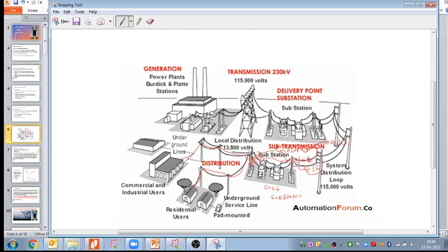And for the overcurrent and the fault, I mean, 5P10, or 5P20 also. Anyone we can take. Generally 10 or 20, these two values mostly we consider. And we can go 5P20 also, right? There is no issue.